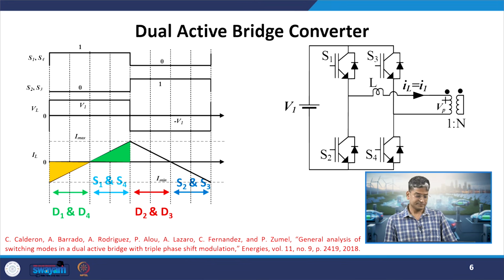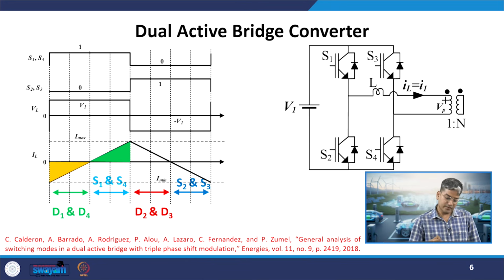Now, if I try to calculate the power which is drawn from this supply, assuming we have some load, if I have this type of operation, will there be any power being transferred? No. Why? If you see the area marked in yellow color and the area marked in green, they will have equal and opposite magnitude. So, they will cancel out each other.